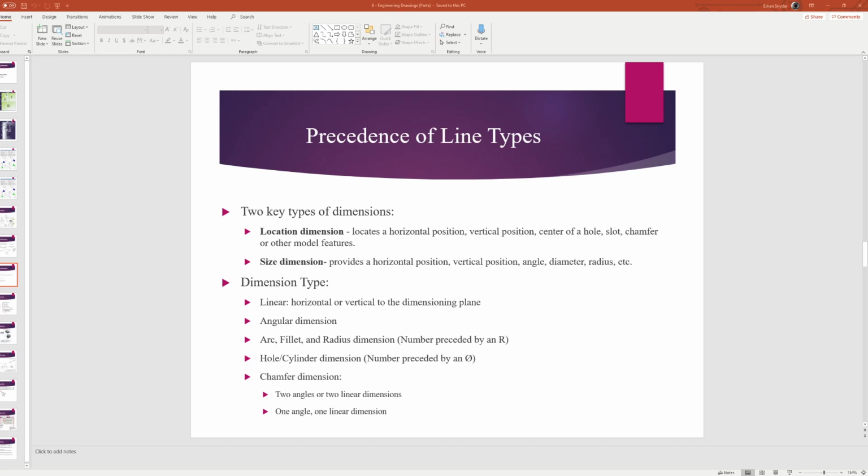So you'll notice that just using a basic smart dimension on a chamfer typically doesn't cut it, because it depends on what the reference point is. If we're considering an angle, you have to ask the question, okay, there is an angle from what? Where is that angle originating? Those are things that we need to consider when we're doing some of our smart dimensioning.